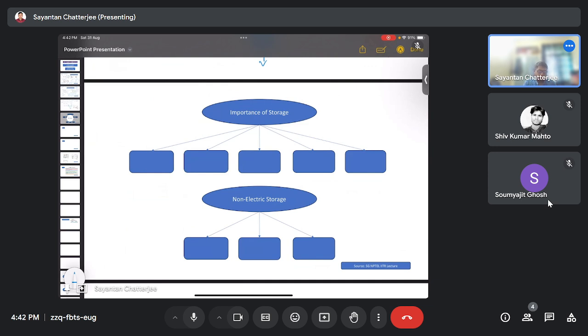Accordingly, we can place battery storage systems or pumped storage systems. We have already discussed the usability of pumped storage systems, where there is an upper dam and a lower dam. During the peak hours we switch on the pumped hydropower plants, and during the off-peak times we pump the water stored in the lower dam back to the upper dam, with the same synchronous generators acting as synchronous motors. So that's the major point of considering these storage systems in place.